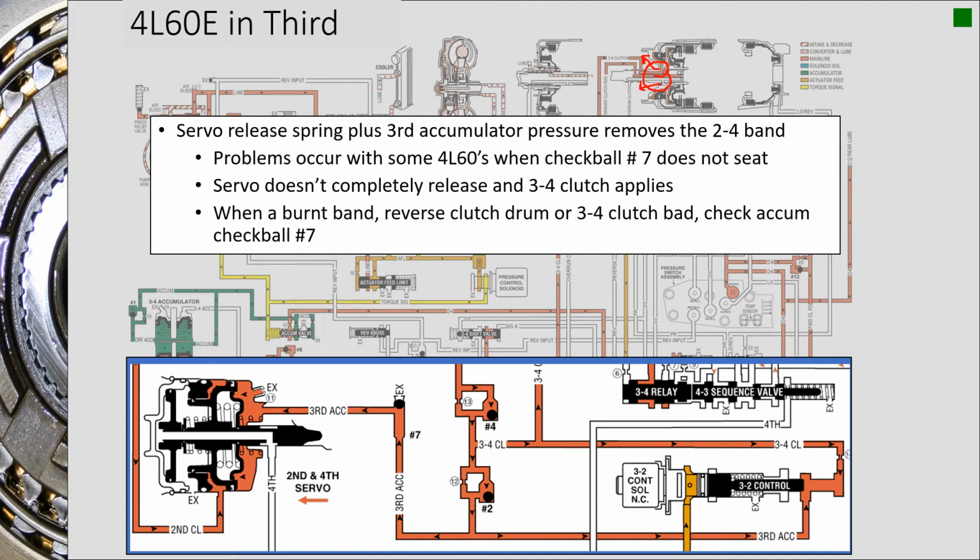It's not going to come out much, but if you put solvent in there when this drum is warm, hot, you're supposed to heat the drum up because the aluminum will expand. If you put a little bit of solvent on top of it and then you air check it, and you see bubbles coming out around that thing, that's not a good sign. It's going to leak, and if it leaks, you're going to burn up that clutch. So what a lot of people do is press that shaft out, put Loctite or sleeve retaining Loctite on there, press it back in, and that usually helps it live.